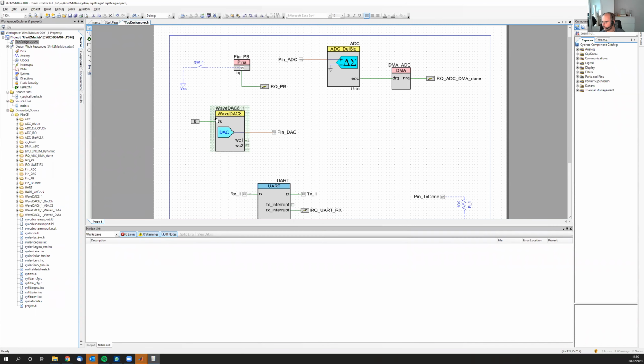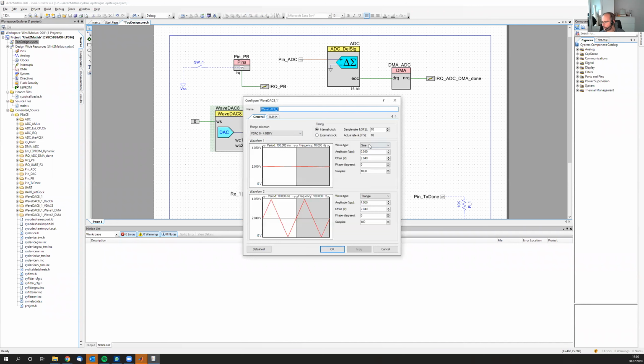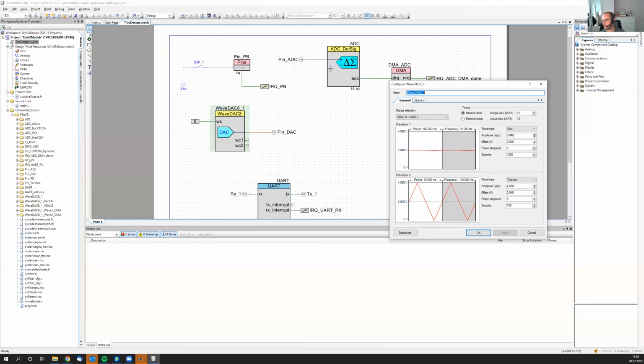Okay. So make sure that the frequency is correct. Now you have two possibilities to do that. One possibility would be that you configure your desired frequency in here, so with playing with the sample rate and the number of samples. Up here, you can see the resulting frequency. You build the project for each frequency, you flash it, you execute your MATLAB script, and then you do this basically 10 times.